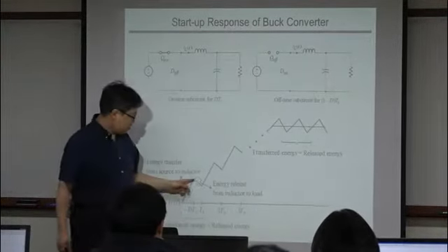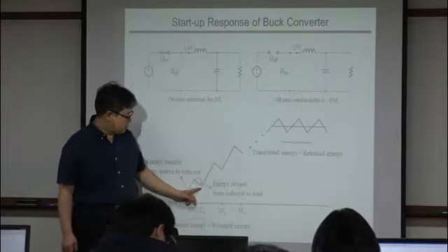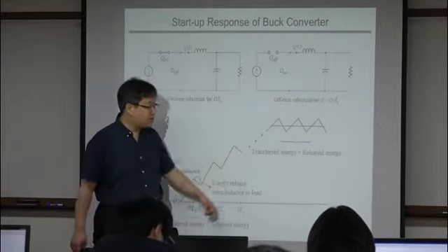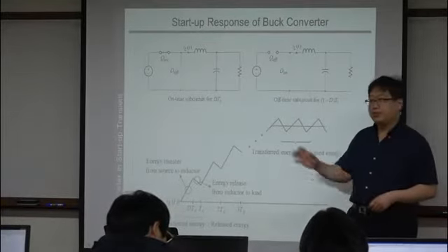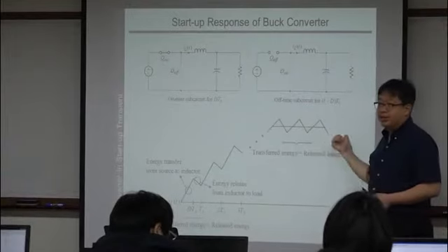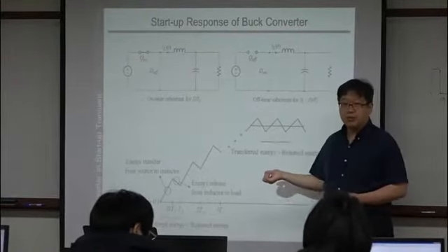So your inductor energy is what? Reduced. Current is reduced. And again, this operation is continuously repeated. And at the steady state, you know the concept of volt-second balance, right? The volt-second balance is fulfilled. Then your amount of increase and decrease are the same.